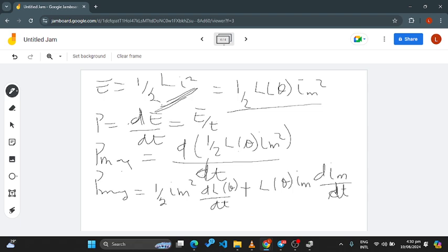Okay, so I have a certain input power, and part of this power is stored in the magnetic circuit. Then it's a motor. So at the end of the day, I'm looking for a certain mechanical power, and that mechanical power should be equal to the mechanical torque that is produced times what? The speed of the shaft, or the rotor speed. So that means the P in should be equal to that magnetizing power plus the P mechanical.